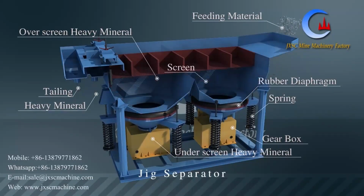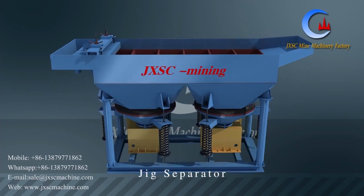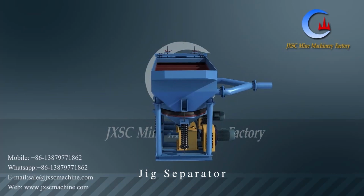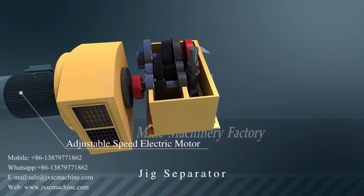You also have a bed composed of other material, and you have to use this bed in order to make your flow go according to your plan and to make some of the particles present in your slurry a little bit harder to lift. And then you have your overflow of material at the end of the jig. So it's quite important to have the feed on one side and the overflow on the other side.